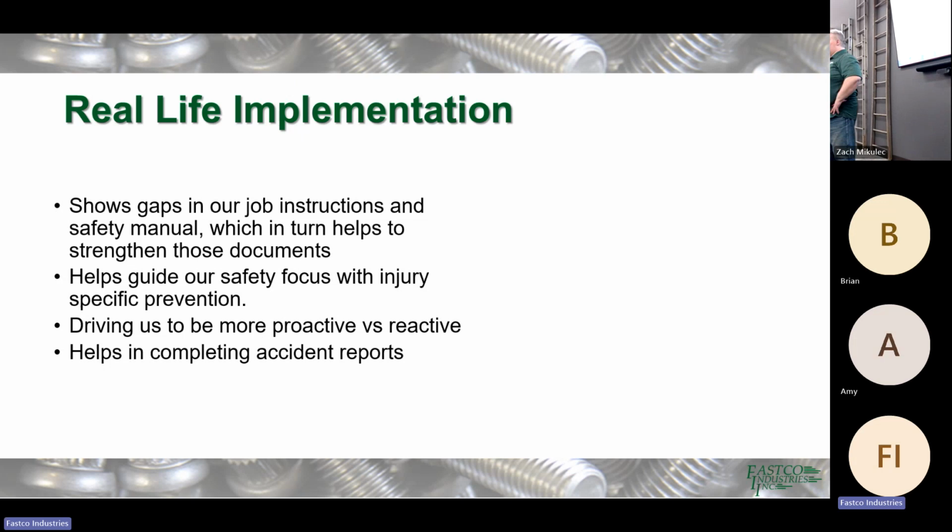What numerical value is significant? In the past, when I've done PFMEAs and FMEAs, we said anything over 100 is significant, right? Do not do that. So those were like our target list, right? Yes. So we wanted to put an engineering control in for everything over 100, for example.